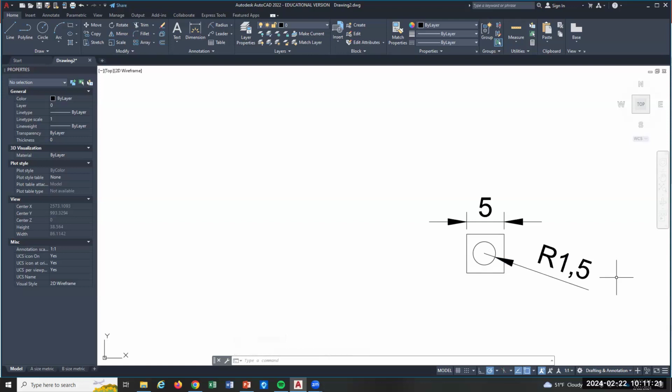Normally, we're not going to want to do that, even in a metric drawing. So when you go to your template, get it off of ISO 25 for the standard, the dimension style. That's not what we want.